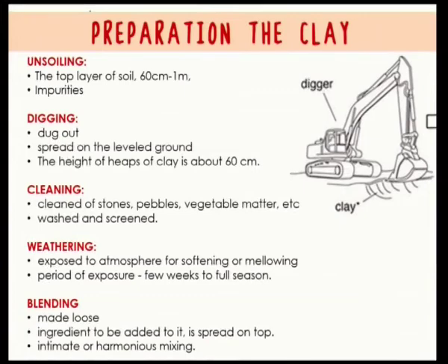Next you have weathering. Basically, in this weathering step, the clay is taken and left exposed to the atmosphere. During the process of weathering, the clay gets softer and mellows down. Because we do the weathering at this stage, the final brick will have a better resistance to atmospheric weathering, because it went through the process of weathering during the preparation of the clay. Now, the period of exposure to the atmosphere can depend upon the location where it is being done. It can be from a few weeks to a full 4 to 5 months.